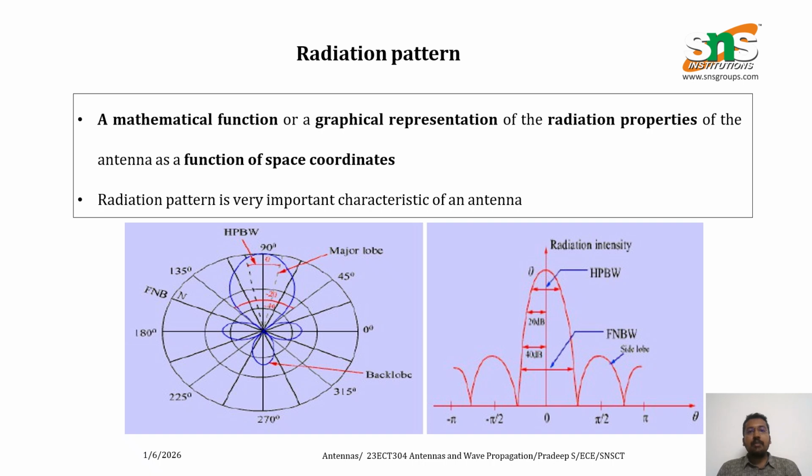An antenna radiation pattern is a mathematical or graphical representation of the distribution of radiated energy in space as a function of the observer's position. Patterns are typically measured in the far field region and presented as a function of directional coordinates. The radiation pattern is often characterized by lobes classified as major, minor, side and back lobes.